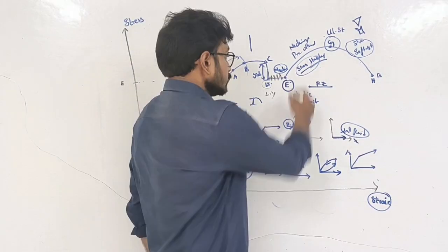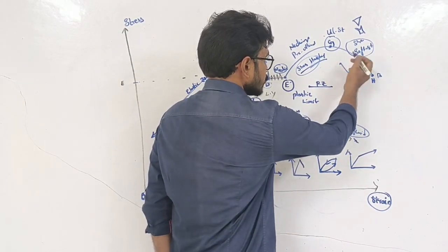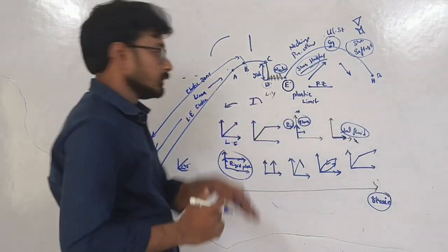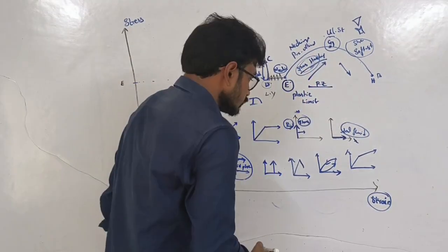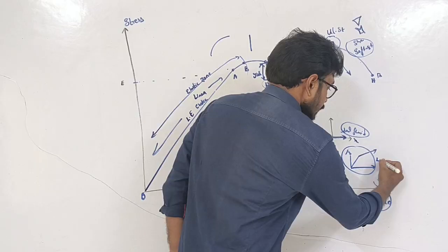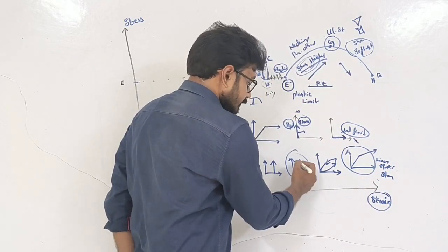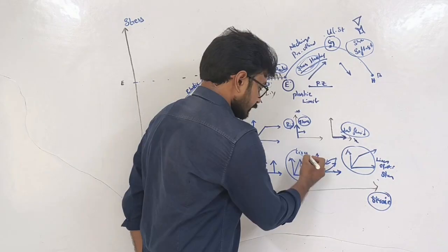Okay, so in this way, we have already discussed that softening will occur in this way, and strain hardening occurs in this direction, softening occurs in this direction. That means the slant of the line. If it is projected upwards, it is strain hardening. So for timing, here this is linear elastic strain hardening, and this is strain softening, right? So linear elastic strain softening.